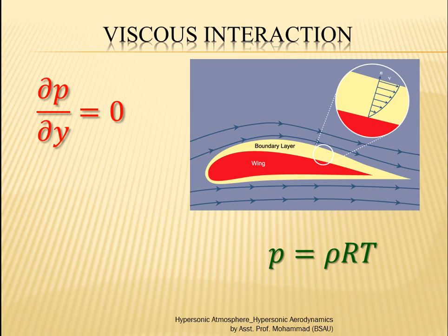Now, a very low density will try to compensate the mass flow rate by increasing the boundary layer thickness. That's very evident, because again we have to have a sufficient mass flow rate to maintain continuity. And a large temperature will cause the viscosity to go high, which in turn will make a very viscous flow. That viscous flow will make the boundary layer grow faster. So both of these conditions jointly cause the boundary layer to grow large.